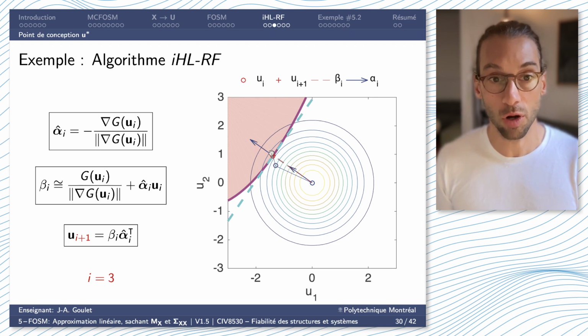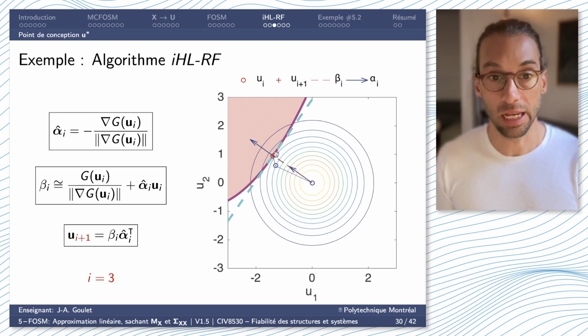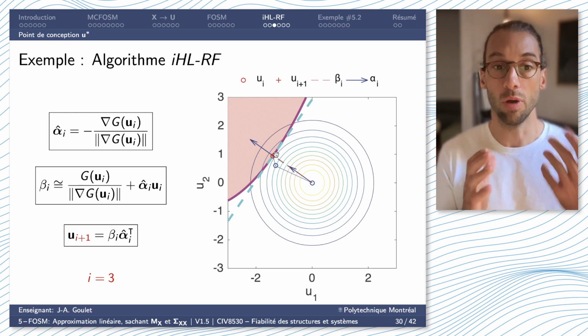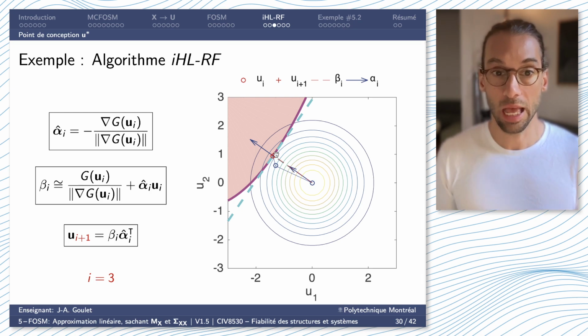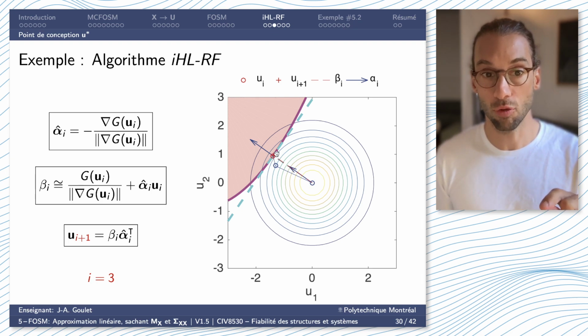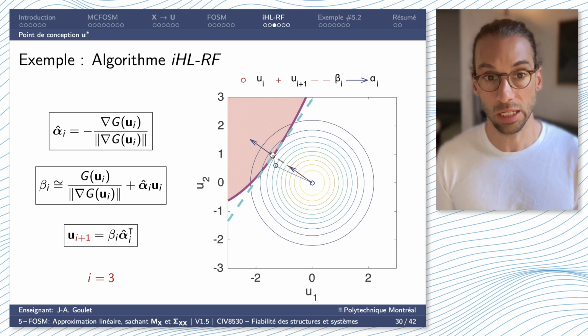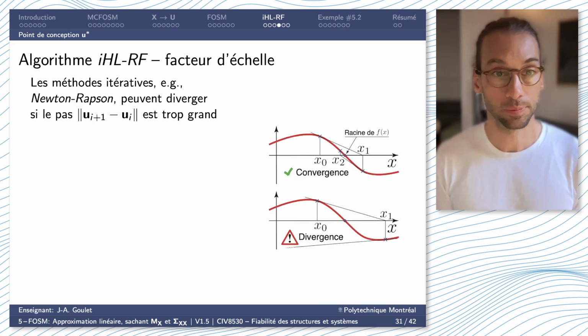And if we do a third point, we see that we marginally move from the second point, and we can say that here we deem to have converged. We have found our design point, and we're going to minimize the approximation error by doing our first Taylor series expansion at this point that is located on the limit state surface that is the closest to the origin.